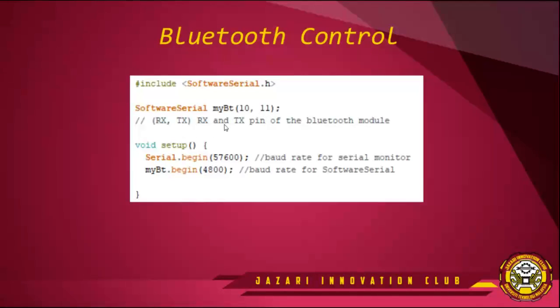That's all. And then the first pin connects to RX of the Bluetooth module. The second pin connects to TX of the Bluetooth module. Okay, so that's all on how you initialize your function for Bluetooth. The data type is the same as the library name. You don't need to install anything because it's already built into the Arduino installation.